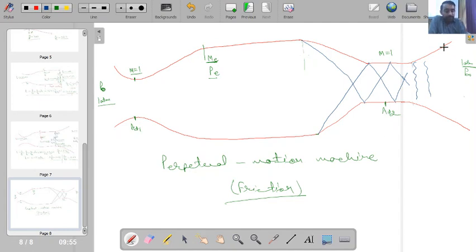Where after the test section we use once again a converging diverging section which acts as a diffuser over here. Now ultimately we see that just at the downstream of this diffuser, say if my pressure is PD, that will be nearly equal to P naught D, because here the Mach number will become very small. So if the Mach number is very small, the flow is almost stagnant, and then static and stagnant pressures become almost the same, and this has to be equal to P infinity.